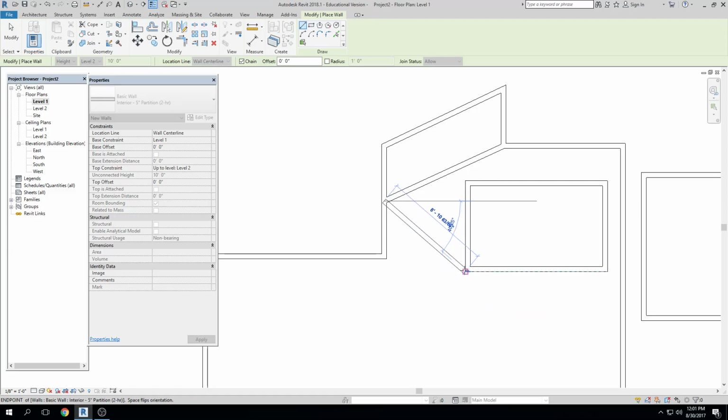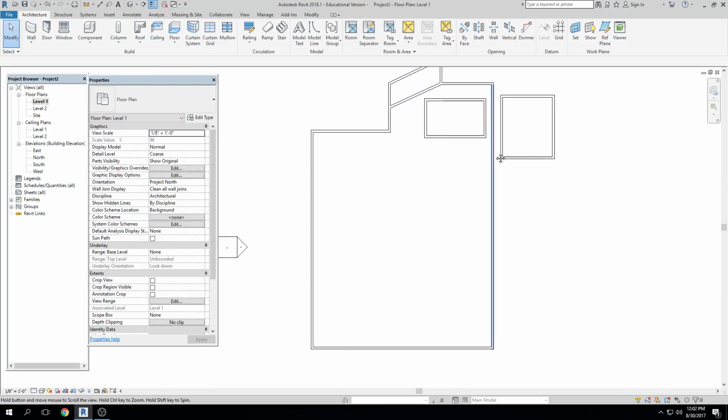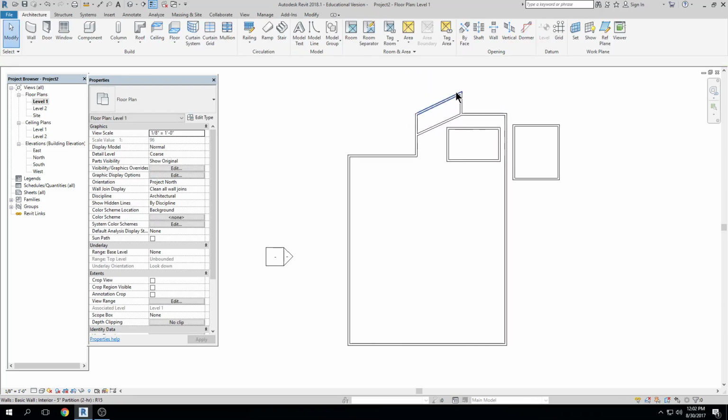A few pop up, right? There's endpoint, there's midpoint, we have nearest, which is showing up in the pink, right? So I get two or three of these. I've got horizontal, similar to perpendicular, right? So I get a few of them popping up, but not as many as AutoCAD. So those are our drawing aids, right? Remember, if I want to select this whole outer boundary, I can hover, tab once, and it picks whatever is chained, connected there.